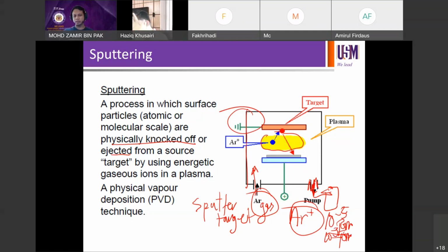So that will create plasma, and then the plasma will actually, this is the target material, say this is ITO that you want to deposit. This is your silicon, for example. In this case, you have your sample down here. You can also have your target mounted a different way. You can put it below or above, depending on the sputtering configuration. The sample can sit on top. You have your shutter in between, like earlier, to control the opening.